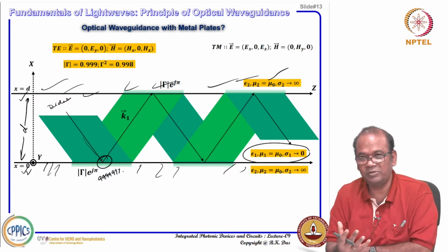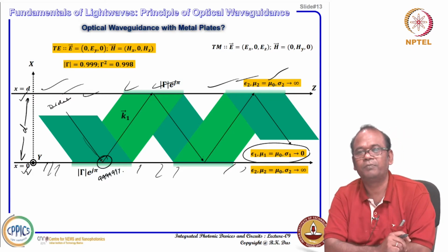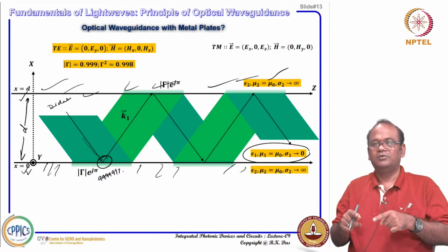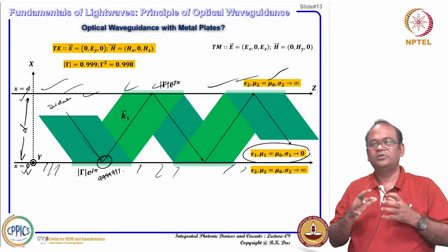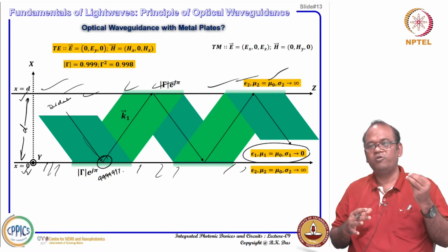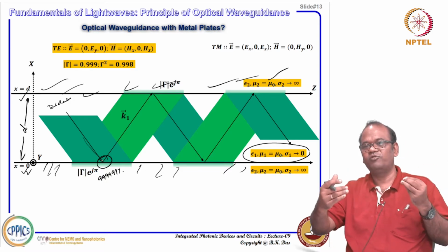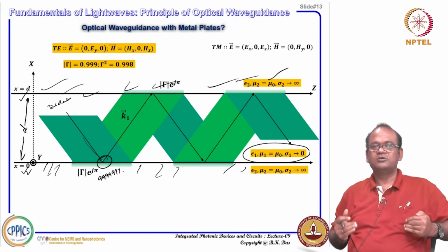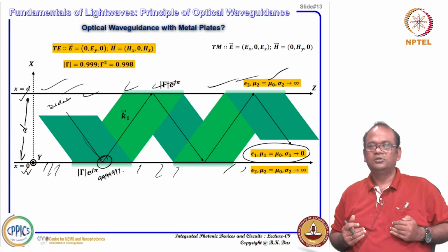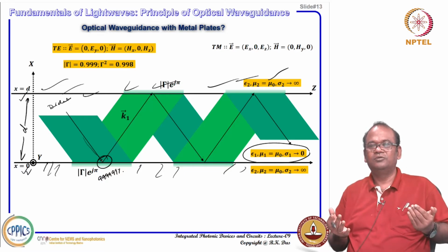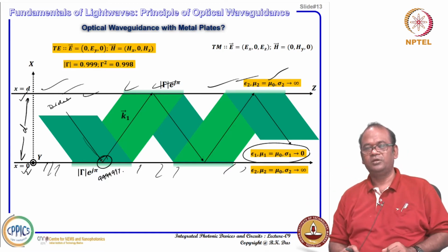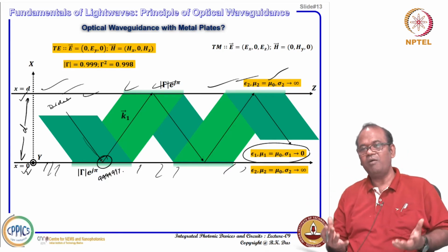So, that is the principle used for the microwave waveguide. This is one dimension; you can make it like a box. Inside the box you can launch a microwave signal, and it will go back and forth by reflection and propagate. That is the basic principle, because metal reflects electromagnetic waves. That is why you can design a waveguide with dielectric inside, making a box, which is a microwave waveguide. So now my question is: what is the problem if we use the same thing for an optical waveguide, for optical interconnect?